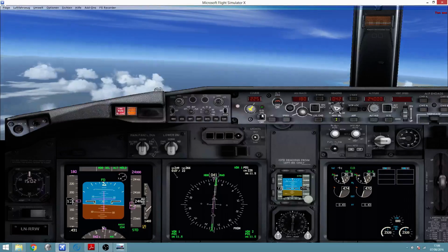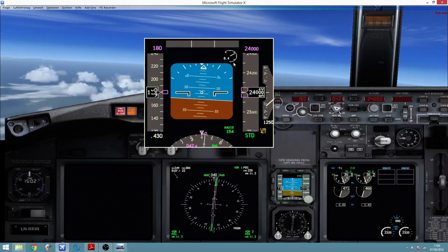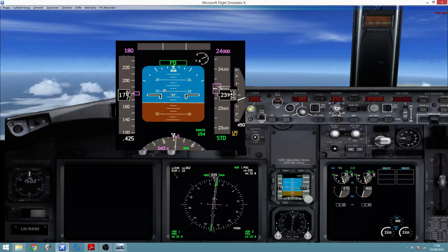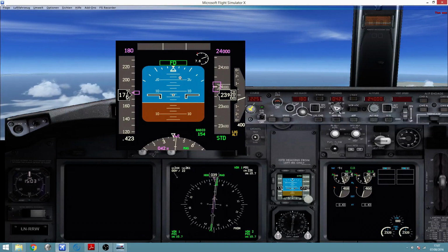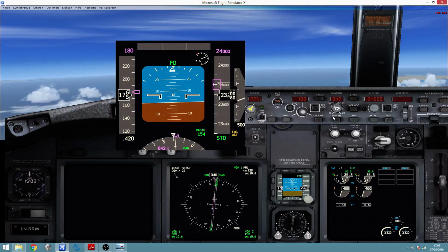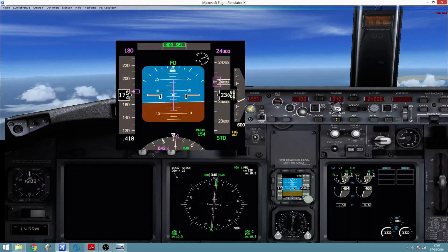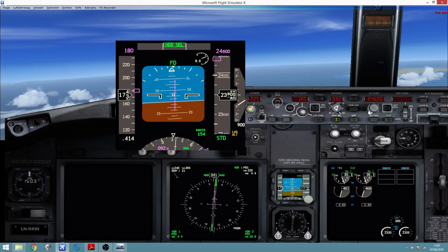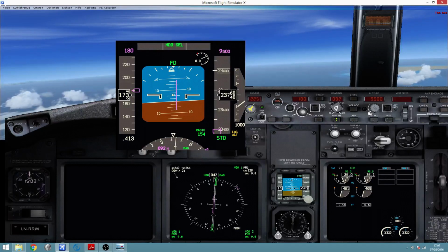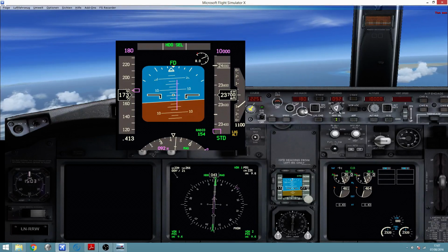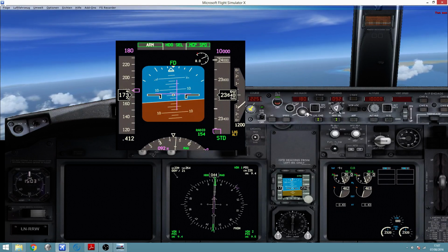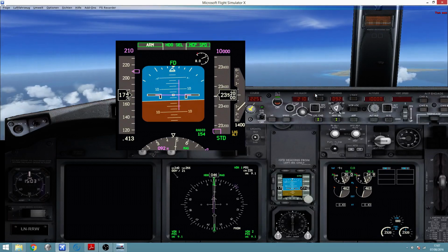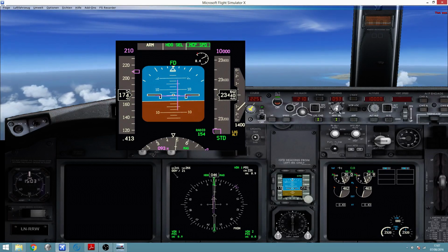And the flight director is this button here that hides or displays a magenta cross that appears on the top of the primary flight display. How does this appear? Well, I have to switch the flight director to on, and now I can select whatever heading I want to fly. Let's say I want to fly on heading 090, and I want to descend down to flight level 100 at a speed of 210 knots.